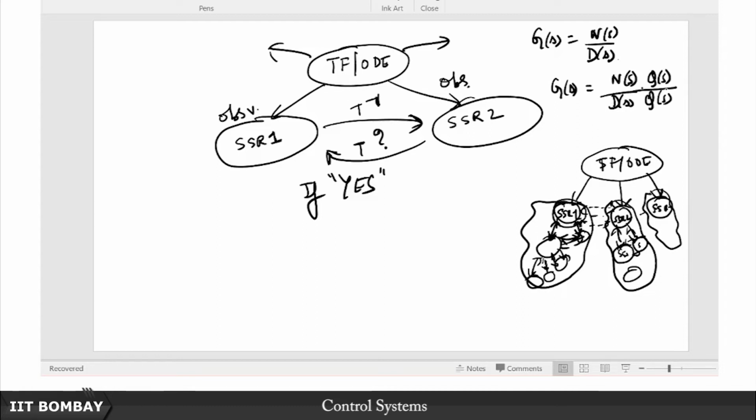So what I mean by state space realization of the same transfer function, I am not referring to these different realizations. If I were to realize this transfer function and you were to realize this transfer function, for starters, the degree of the denominator polynomial in my case will be smaller than in your case. QS is an additional polynomial, a common factor.